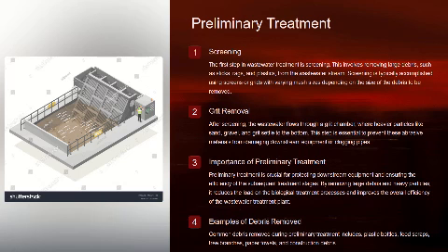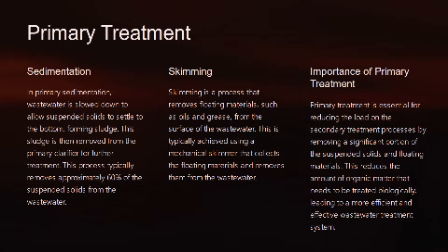And the reason why these 2 stages, as part of the preliminary treatment, are very important is because they are going to be the pace setters for the next stages to come. That is to say, you want to remove the big materials before you start removing the small materials. It makes things much easier that way. Let's move to the next stage, and that's the primary treatment.